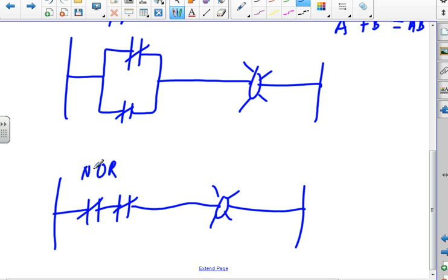On page 94, I see a high level alarm going to the, fine. So now it's a matter of, I'm not going to run wires from a component to another component. I'm always going to go through a terminal board on the way to the other one. So in this picture here, we have a terminal board for 1, 3, and 4. My wires go through the terminal board before I get to the motor controller.